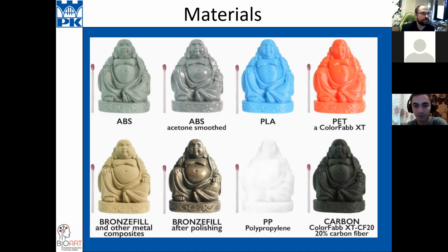The shrinking range is very high because it's more or less 20%, but after regular FDM printing, you can get things made from solid metal, almost solid, from sintered metal. Yeah, we have some gaps between particles. But this method is very nice.